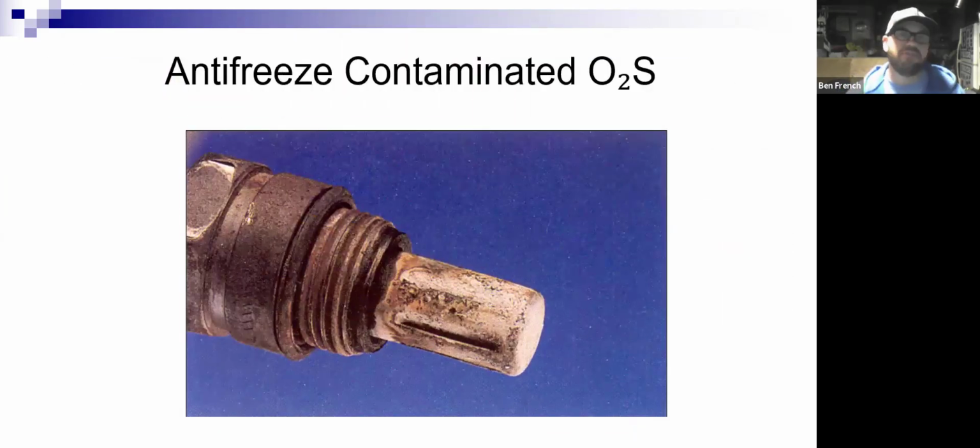Here's probably the most common one that I still see: you have a car that has mechanical problems. It overheats, it blows a head gasket, and it's burning coolant in the engine. Well, guess what? Not only do you have to deal with the head gasket and that mechanical job of replacing it, maybe having the head milled and all that type of engine work, but burning the coolant likely wiped out all your oxygen sensors. If that's a V8 engine with multiple sensors, you could be replacing 4 additional sensors.